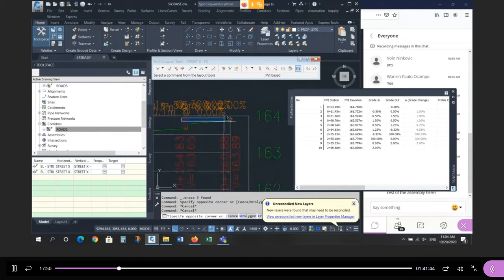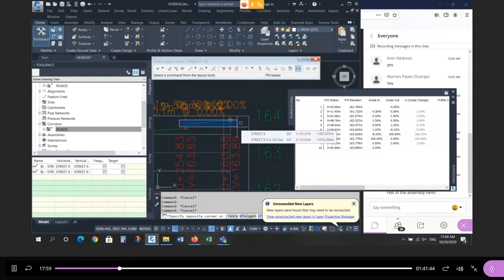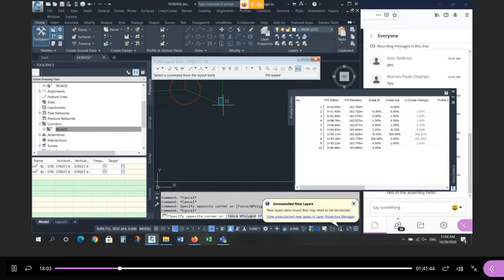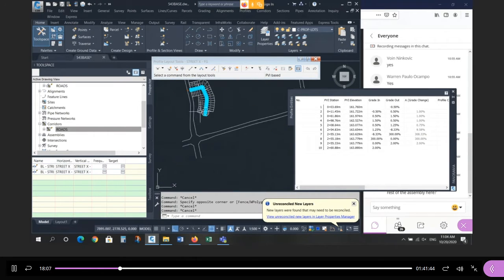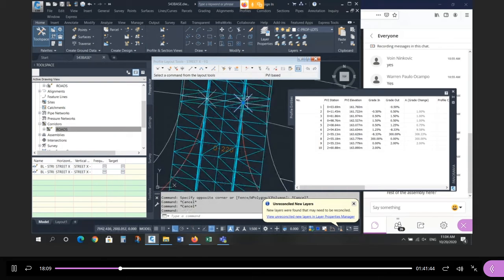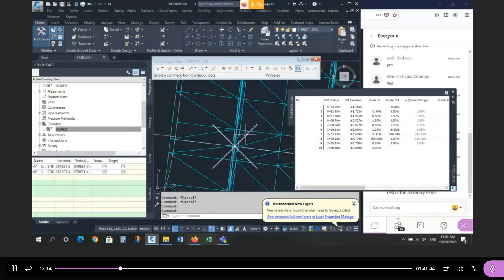All this other stuff is just a filler. This is just for reference. You don't need any of this to do the design. As a matter of fact, this will be taken care of when I go around the cul-de-sac. But this point is critical right here. You need elevation. So here's what we do with those 3 points. I'm going to grab that point. That's the beginning. There's basically the middle of the profile, and here's the end of the profile.